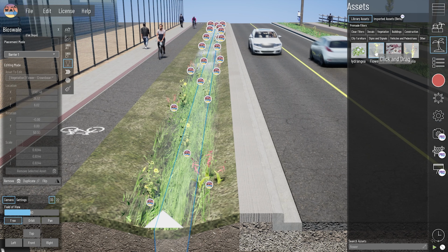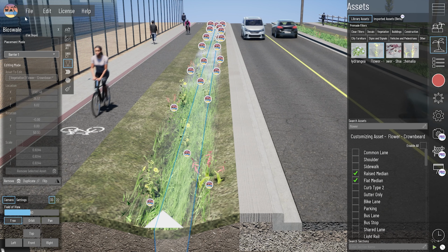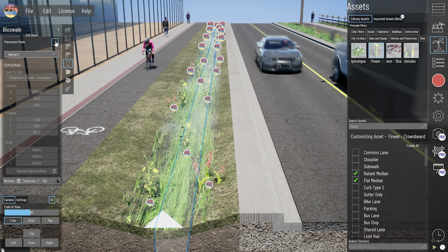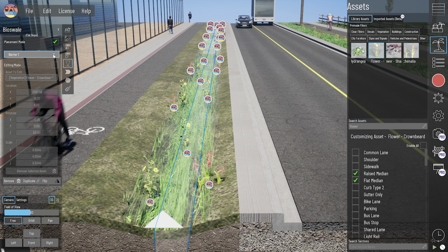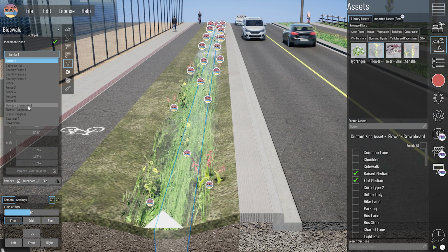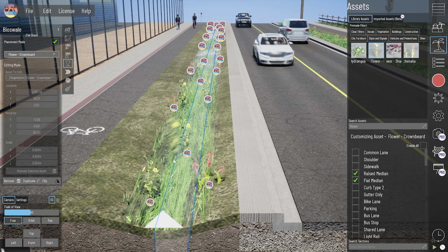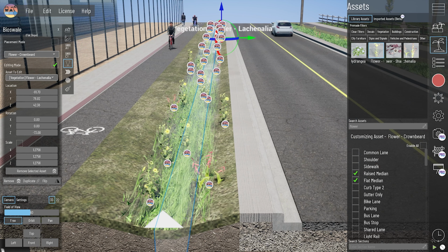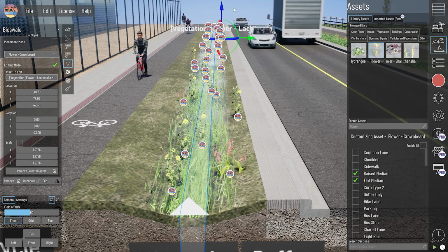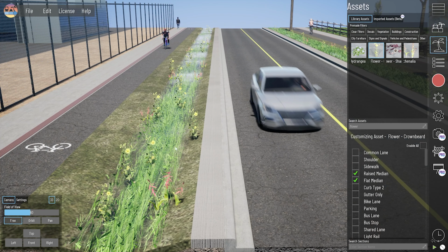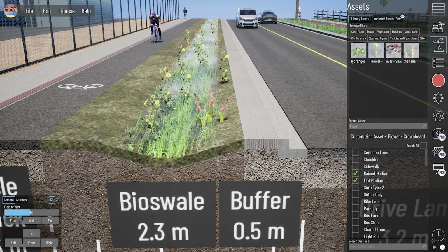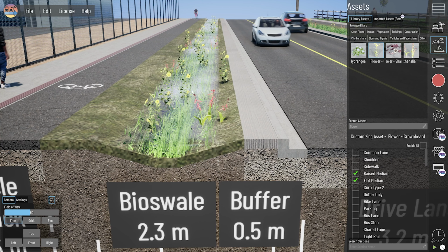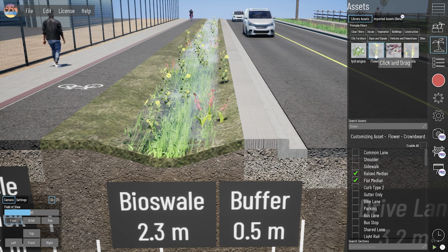Otherwise, what you can do is make sure that that asset is in the placement mode. So if you select a section, go to asset placement and turn on placement mode, as long as it's populated in this list, which I've done here. So flower crown beard is now placeable. Now I can just click a lot and place those down and get those in rather quickly. So it's nice if you're looking at another option for maybe some randomly assorted vegetation elements that pop up a lot. That could be a nice way to do it other than clicking and dragging those elements in one at a time.